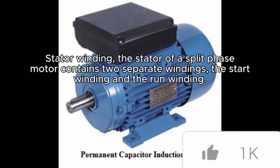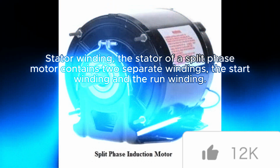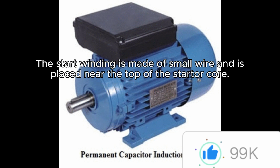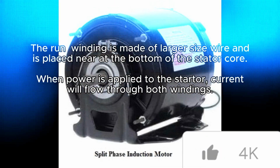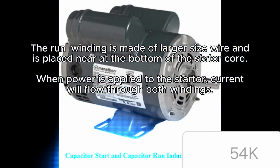Stator winding. The stator of a split-phase motor contains two separate windings, the start winding and the run winding. The start winding is made of small wire and is placed near the top of the stator core. The run winding is made of larger size wire and is placed near the bottom of the stator core. When power is applied to the stator, current will flow through both windings.